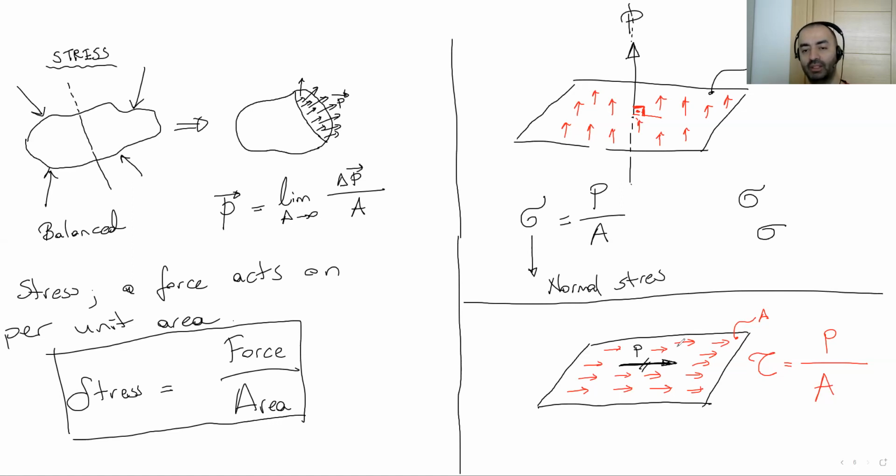If we have a normal stress or axial stress, which is perpendicular to the system, we check it with the axial stress capacity. That's why we make this division. So at the end of the day, the calculation of the stress is the same, force over area. This is really, really basic.